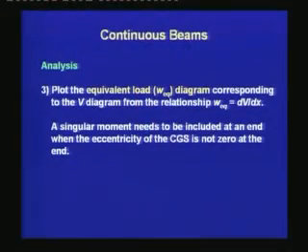The third step is to plot the equivalent load or Weq diagram corresponding to the shear diagram from the relationship Weq is equal to dV divided by dx. Thus, from the M1 diagram, we are calculating the shear force diagram. From the shear force diagram, we are calculating the equivalent load diagram. We had talked about this equivalent load diagram for simply supported beams. For a simply supported beam, the equivalent load is always upwards, and we said that it was the upward load which balances part of the external load.